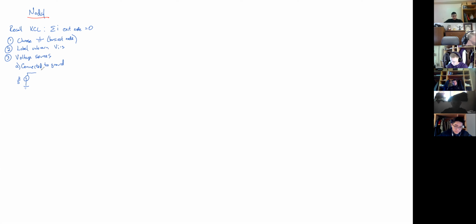And we're in the Laplace transform domain, so I'm going to make mine a Laplace transform, capital V1s, because we're in the frequency domain. Then we can get rid of our V1. This is no longer V1, it's just 2 over S, because this side is hard connected to ground.